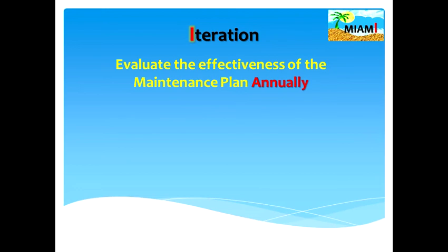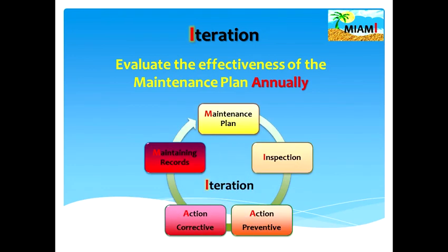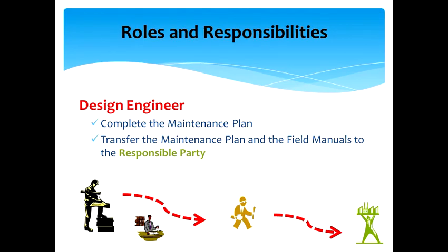The Stormwater Management rules require that the effectiveness of the maintenance plan be evaluated annually. The maintenance plan must be adjusted according to the resulting evaluation. Maintenance personnel shall provide comments and suggestions to the manager for consideration on how to perform the work more effectively in the future. The manager shall also review the inspections and preventive and corrective records to find whether an improvement can be made.